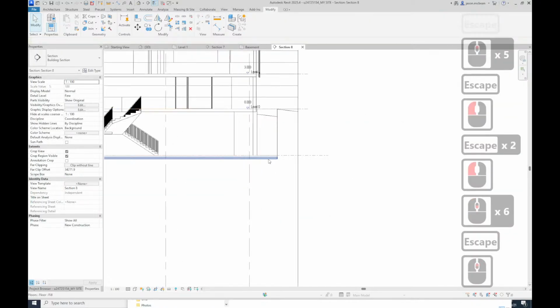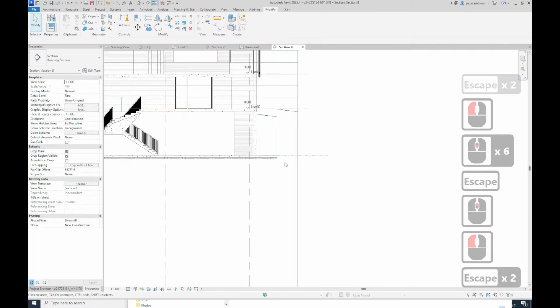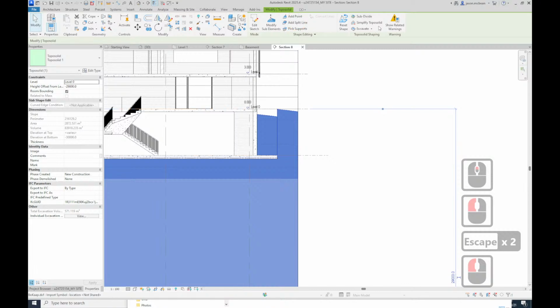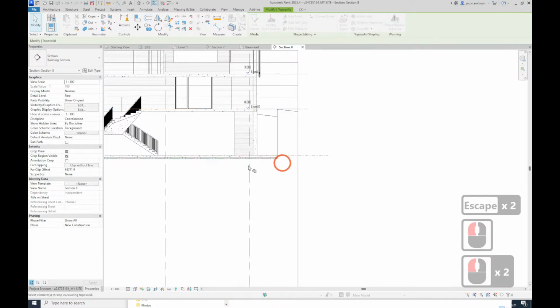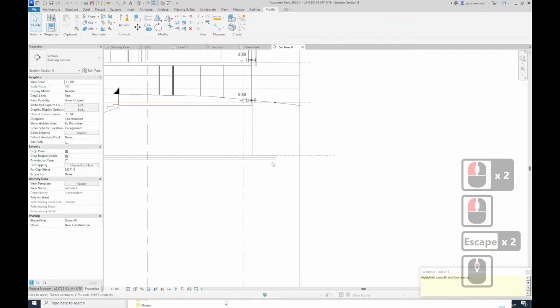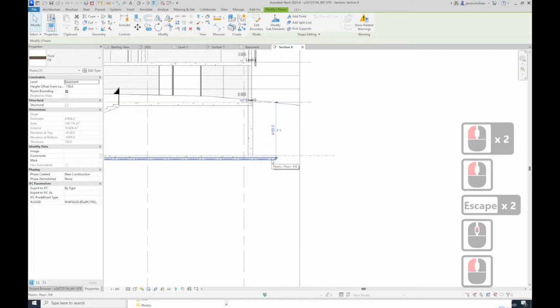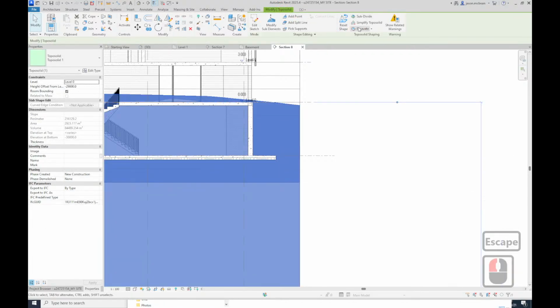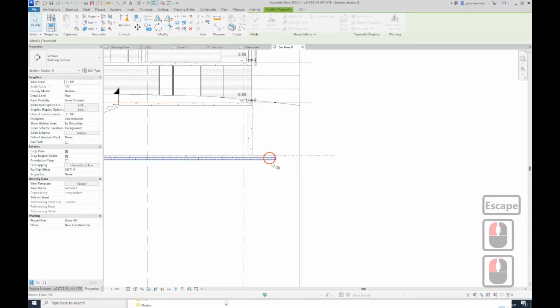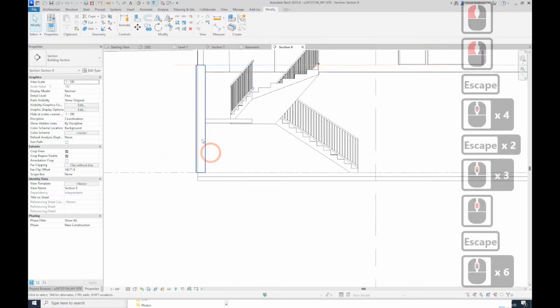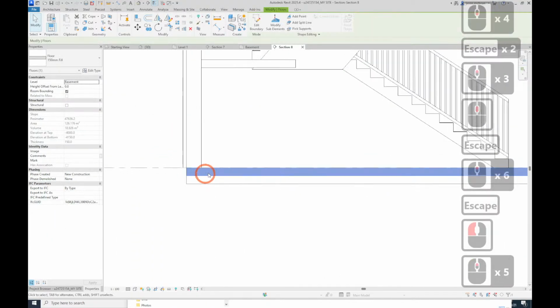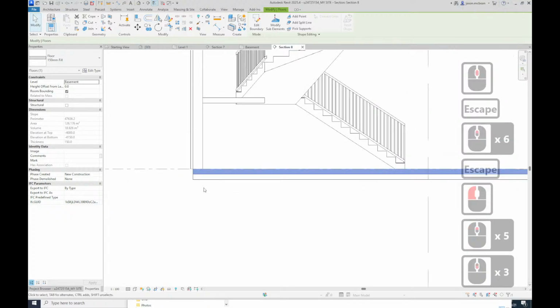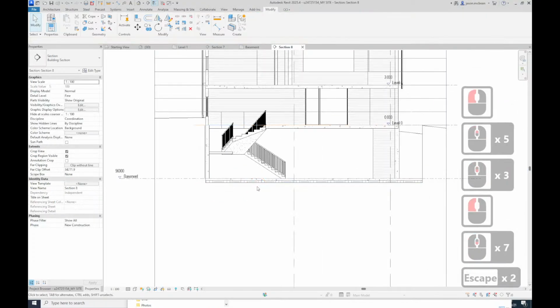Okay. So this layer becomes my excavate layer. Okay, so this, I'm going to go and say, remove excavation. I use this layer rather because that's my fill. I know my slab sits on top of it. It makes working this way much easier. So I'm going to go excavate. Because sometimes you'll find that this will actually stop in there and your wall goes down sometimes. So this I use to excavate everything. And I know my slabs and everything sit above.